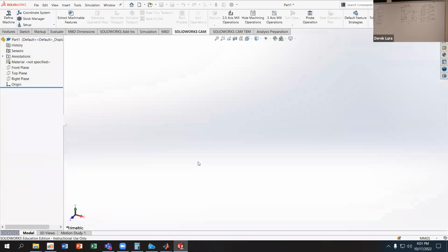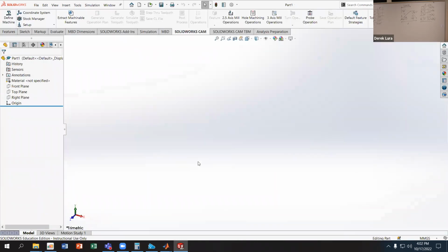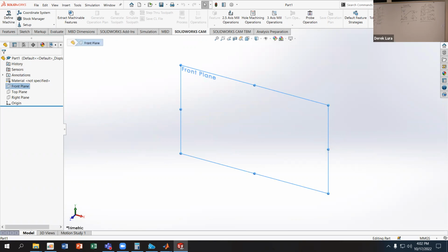I don't need to change anything, so if I do it in millimeters, my standard precision is 2 decimals. And 2 decimals of precision in millimeters is pretty tight. 2 decimals in inches is not very tight, right? So there's a big difference between 0.1 millimeters and 0.1 inches in terms of what that means. So let's stay in millimeters.